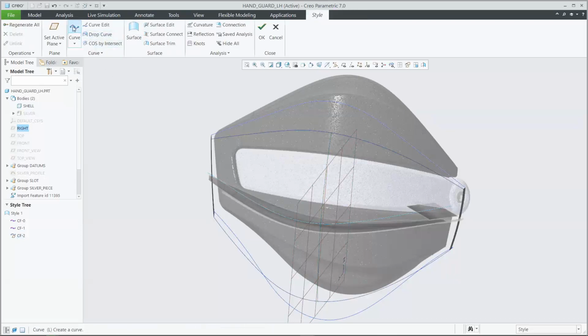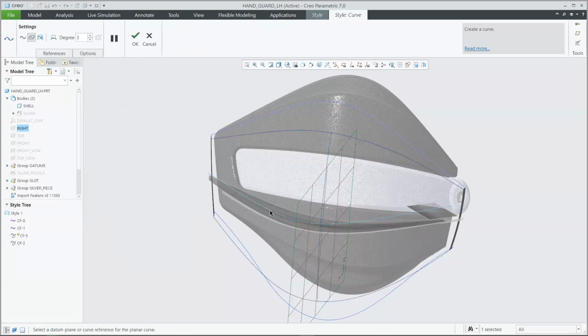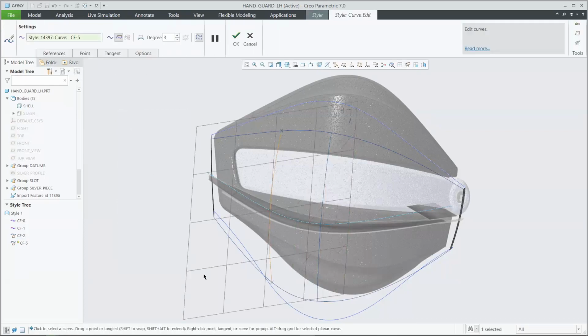And once we have that one good to go, we'll place a few more along here. Maybe this time we'll use the radial planar option. This means that I'll select on a point on one of these curves, and the plane that's being created will be normal to the profile sketch that we selected. Just making sure that it's intersecting with the other curves as well.